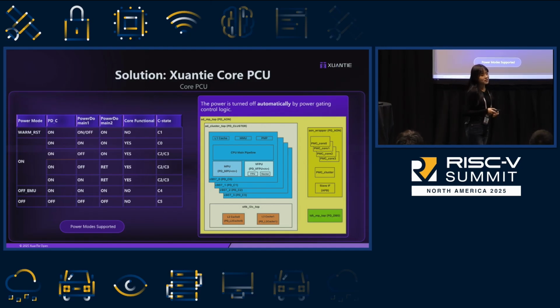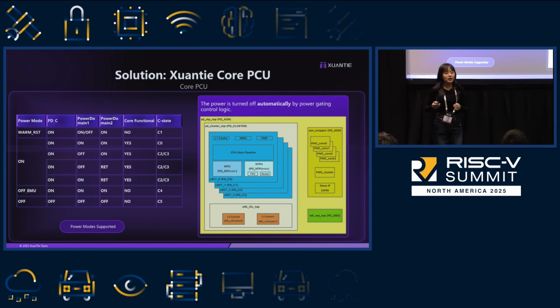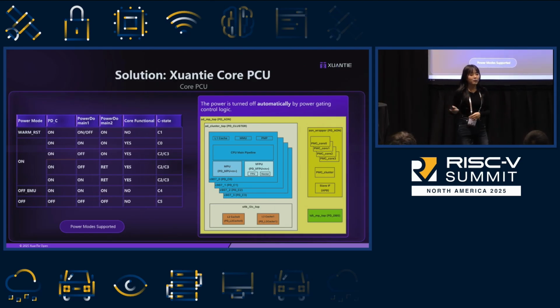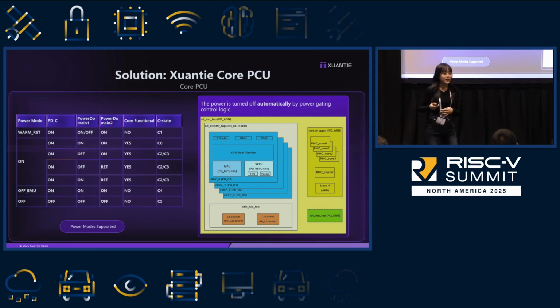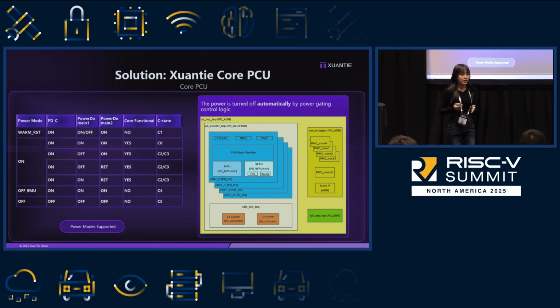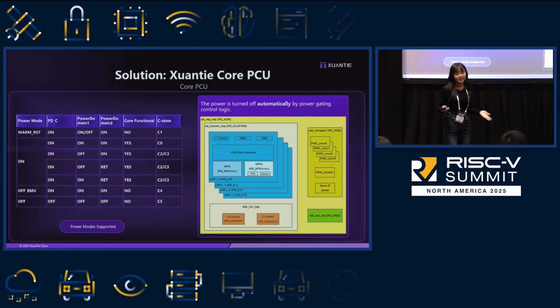We define the power management unit close to the core. So when the core dives into the deep sleep state, it will first notify the PCU that, okay, now I'm going to sleep. So when I go to the WFI state, please help me to power down and clock gate me. So everything just happens automatically. It's like when you're going to sleep, you tell your cell phone, when I close my eyes, could you please help me turn the lights off? So everything just happens magically, right?